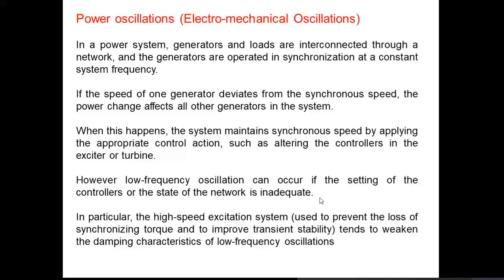But we can say that such low frequency oscillations may exist whenever you have some disturbance, and following the disturbance you change the settings of the governor controllers, right? That change in the controller gains, or maybe the system network itself, may result in low frequency oscillations for the change in the operating condition, right?